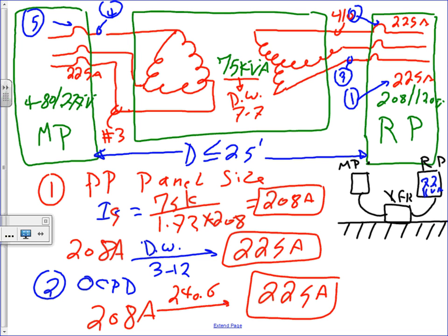Right, that here. Do I need another fuse or circuit breaker right here? No. Why? Because they are within 25 feet of each other. They call it the tap rules. You're going to see in a second, the tap rules. Can I have thumbs up that we got that one? Cool. Let's go to the next.